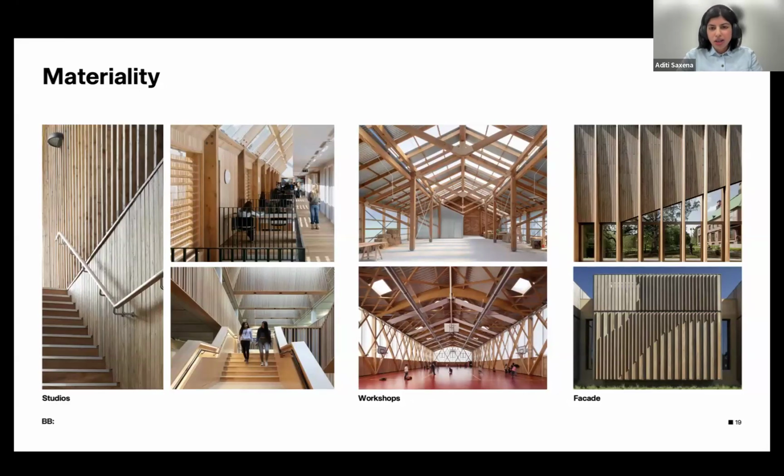However, the budget did not allow for that. So instead, we began exploring a hybrid frame and facade solution. And rather than see this as a negative, we actually saw this as an opportunity, because to achieve the large, clear spans in the workshops in timber, we would have required glulam beams in excess of 1 meter depth, pushing the envelope even higher. So actually, it was more efficient in terms of material use, cost, and space to move to a steel frame within the workshops.